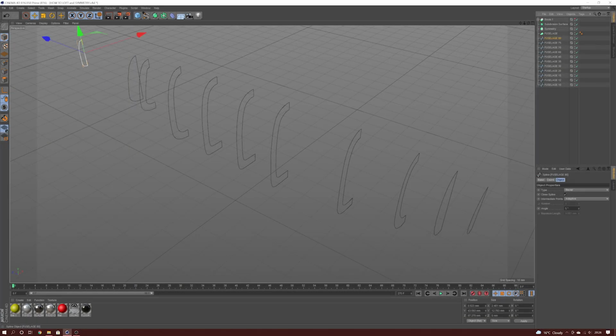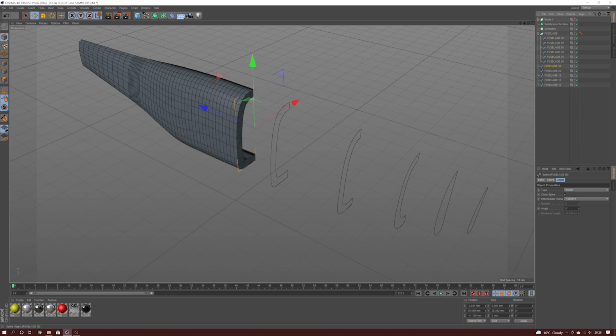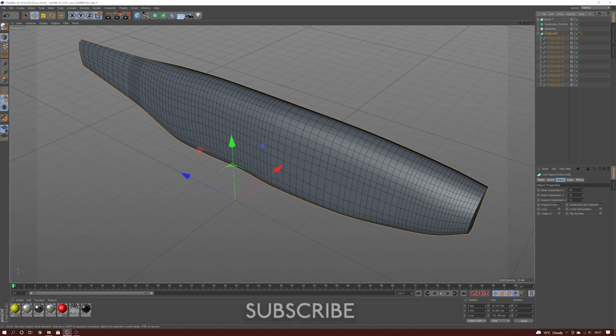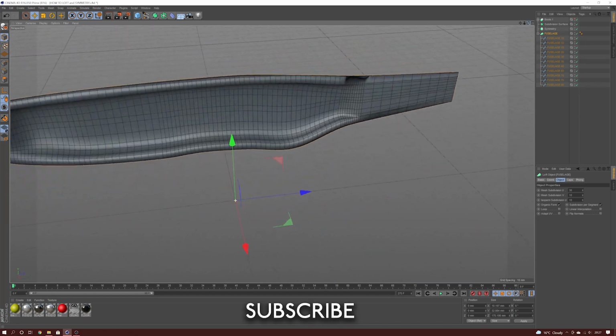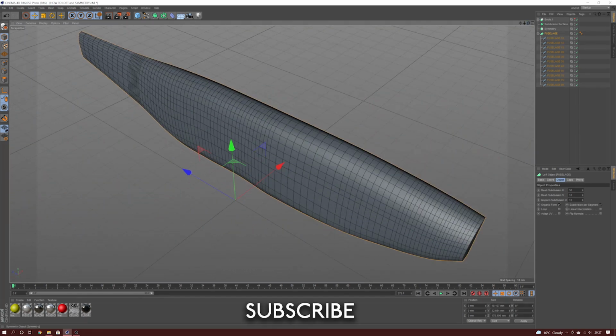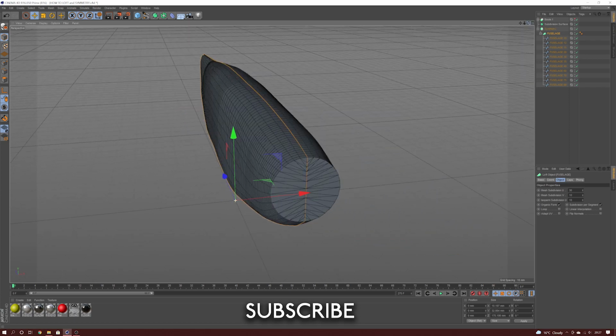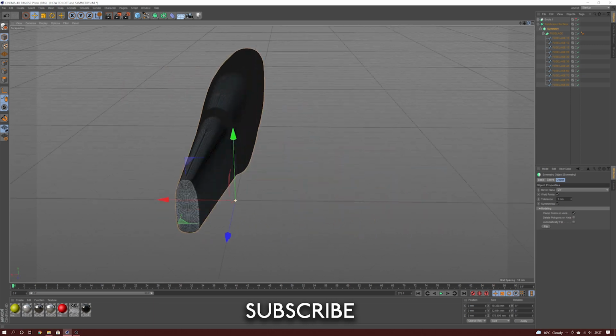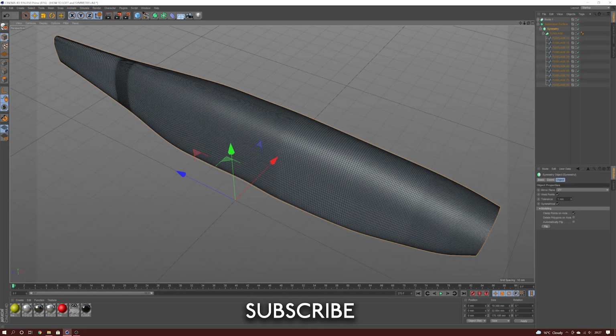A good example of the loft tool in use is creating a fuselage for an aircraft. From scanned drawings, splines have been created from the aircraft sections. These are then aligned and progressively added to the loft tool, creating one half of the fuselage. The loft is then mirrored to create a solid object and smoothed out by creating further subdivisions to the surface.